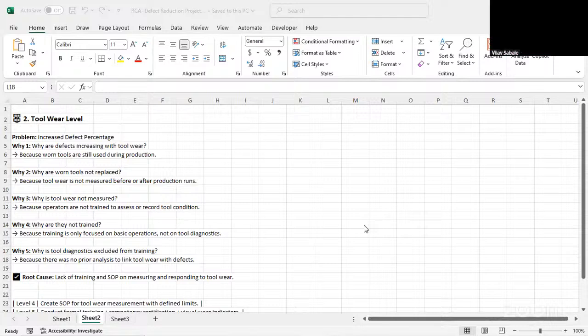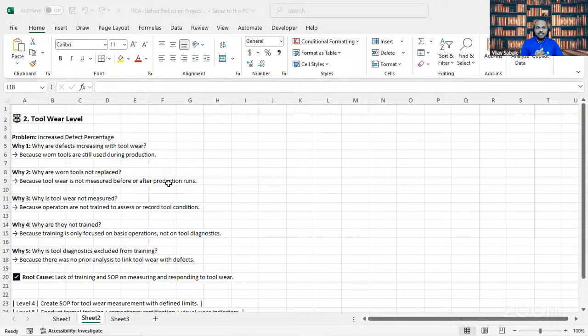Okay, so maybe you can go through the recordings and catch up, right? Sure. So there are 3 factors. Let's discuss 2 here. The first we identified as the inconsistent injection pressure, and because of that we got the problem, right? Second, we saw the tool wear out, right? These are the 2 significant causes we have identified.